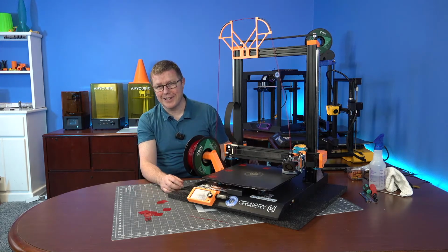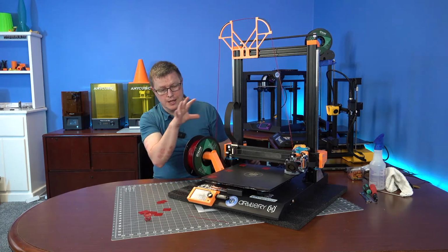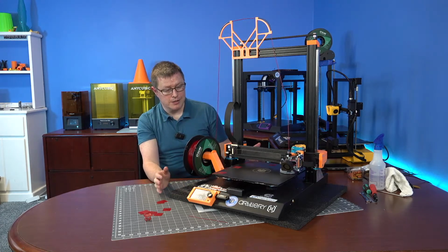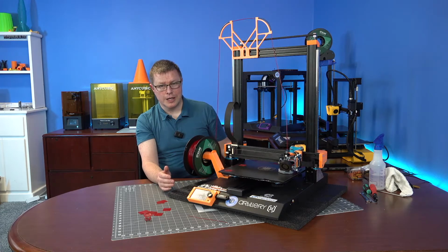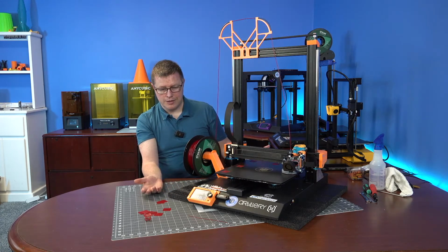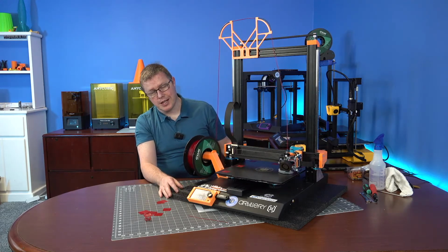I accidentally discovered that issue when I was initially setting up the BL Touch firmware. Why is it so terrible? Then I was messing with it in my garage when it was super cold, and it was perfectly fine. Okay, this is weird. And then I go in the house and it's terrible. Oh, I bet you my stepper drivers are getting hot. I thought about that.